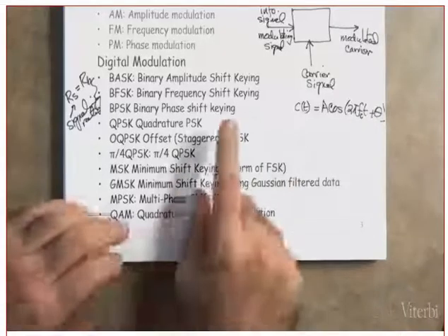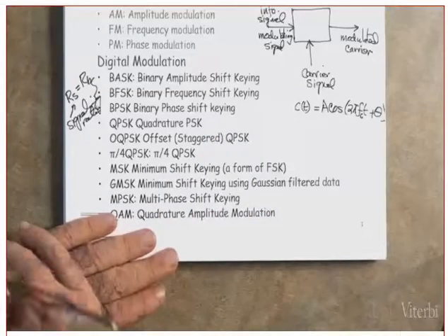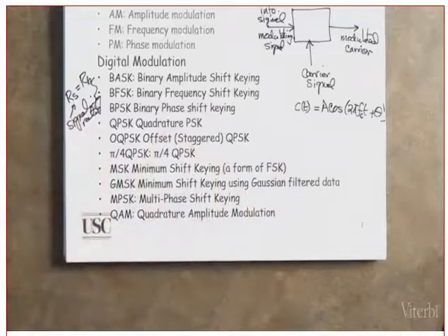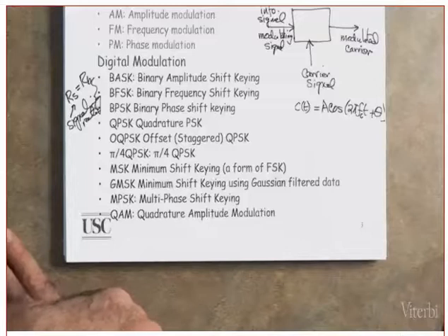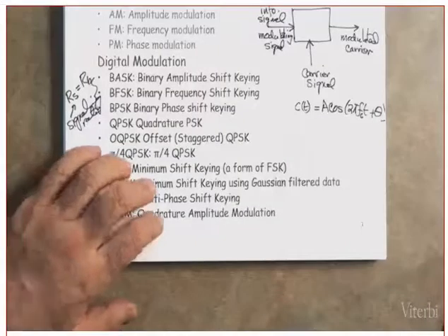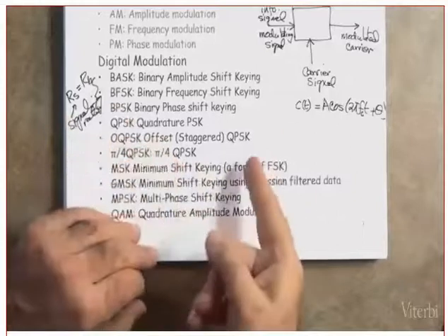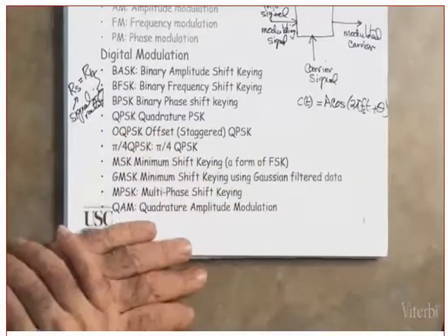It is smooth. And remember always, when the signal in the time domain is smoothly changing, that implies that the side lobes will become lower. Are you following me or not? Why? The spectrum will become more compact rather than widely spread. What is the spectrum of a square pulse with no shaping? It's a sinc type, which keeps going on and on. Whereas this one, we will see that the bandwidth or the spectrum is more compact through the shaping of the signal.